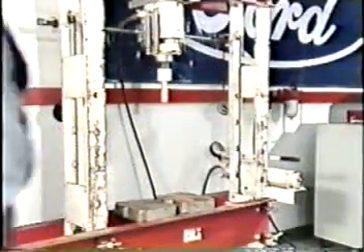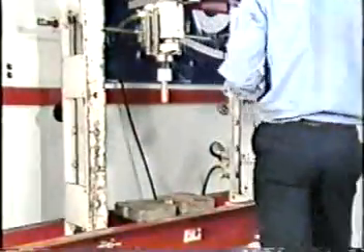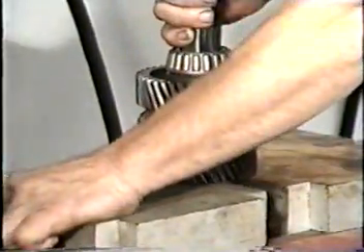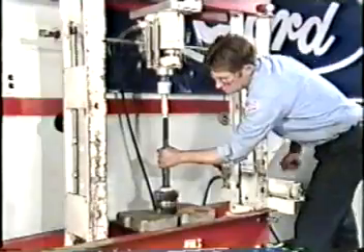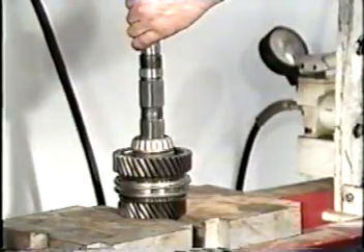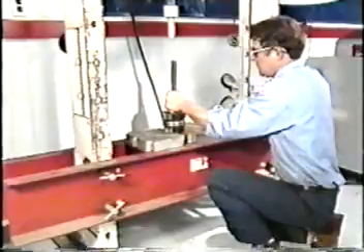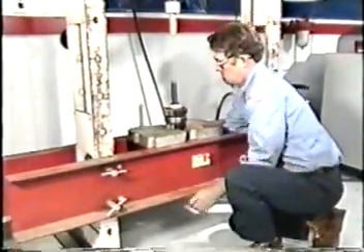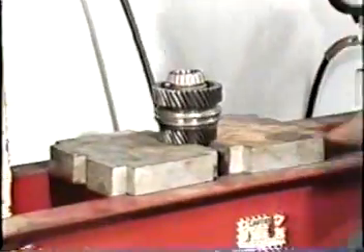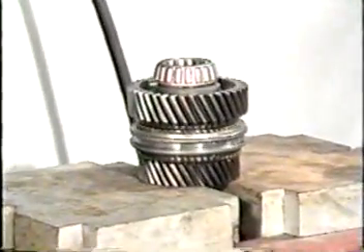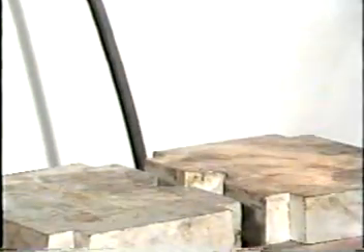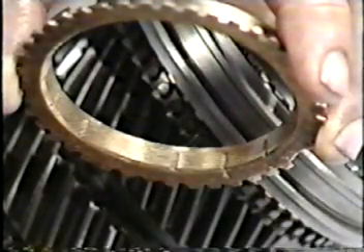Now, disassemble the long side of the shaft with the press. When using the press, make sure the flange does not contact the press cradle. The components on the long side of the flange are pressed off as a unit: the center bearing, first gear sleeve, first gear, needle bearing, first-second synchronizer, first-second synchronizer ring, and needle bearing. Once the output shaft is disassembled, a closer inspection of the synchronizer assemblies can be performed.